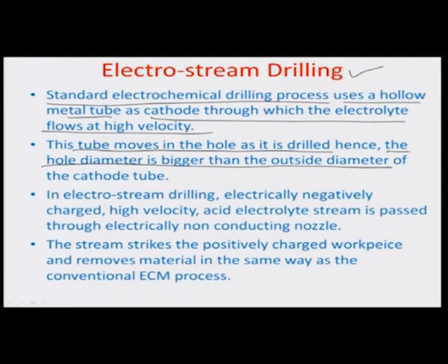So there is dissolution of material along the drilling face and also along the drilling sides of such a tool, which would typically result in oversize of the hole diameter that it would be intending to formulate.